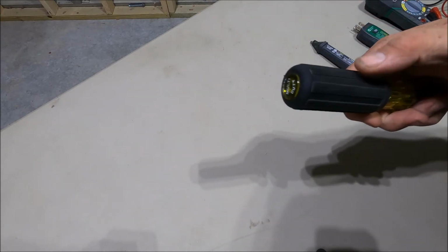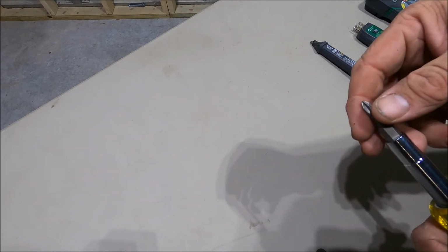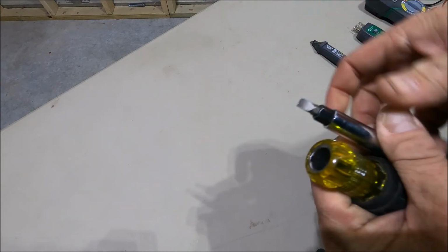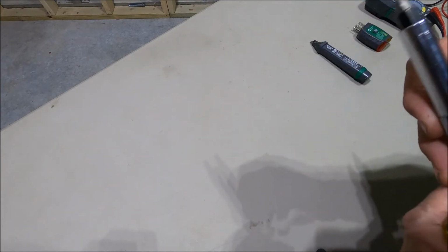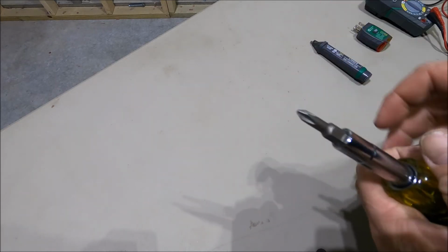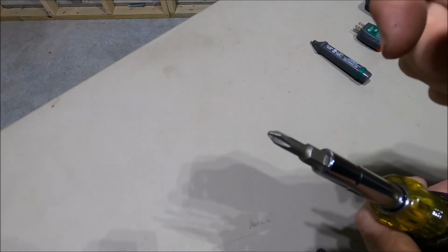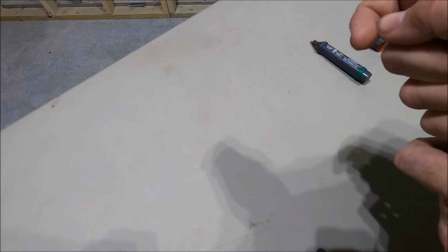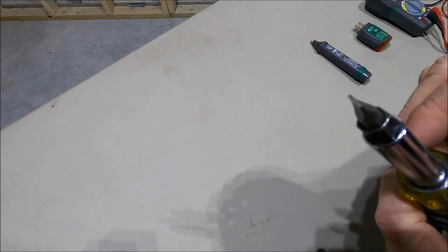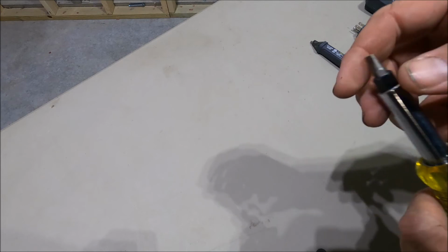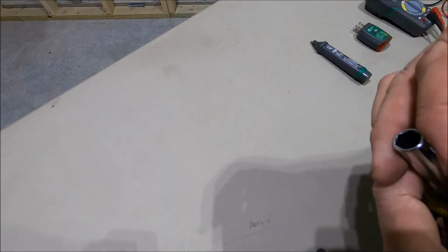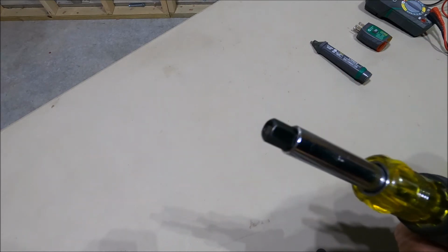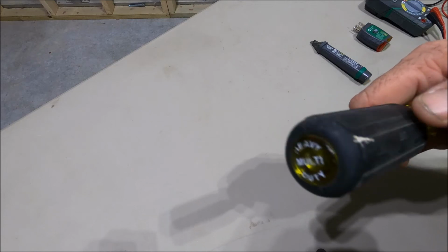The next tool is an actual electrical screwdriver. What I mean by that is it's insulated on the end, and you can see it has a bunch of different bits in it. You'll want a bunch of different bits based on what you're doing. Say you're wiring up outlets: you want a big Phillips bit to screw in the screws on the side of the outlet. But if you're taking off cover plates, you need a small flathead bit. And some of these double as nut drivers, so these are really handy. But what's most important is they're also insulated.